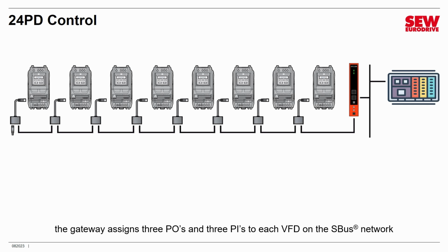As you recall from the last session when we talked about the external gateway, you learned that the gateway has up to 8 VFDs on an S-bus field bus on one side of the gateway, and then a different field bus on the other side, like an Ethernet-based field bus. The PLC talks to that field bus, and then the gateway passes the traffic over to its local S-bus.